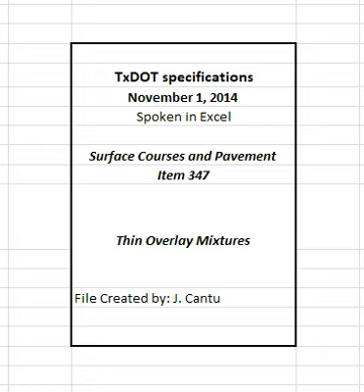Table 7. Laboratory mixture design properties. See table in specifications. 1. Unless otherwise shown on the plans or approved by the engineer. 2. May be adjusted within the range of 35 to 100 gyrations when shown on the plans or specification or when mutually agreed between the engineer and contractor.